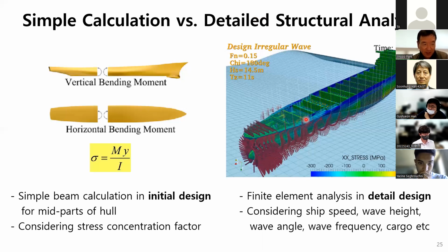In this detailed analysis, we apply actual variable pressure loadings over the whole ship outer surface, considering ship speed, wave height, wave angle, frequency, and also internal cargo.